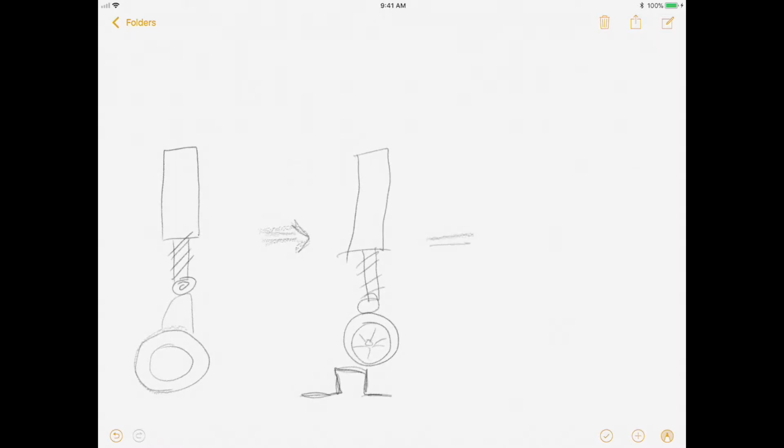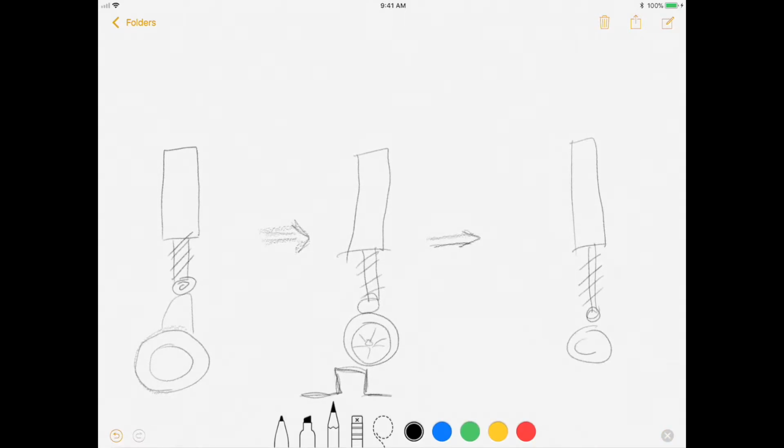And thirdly, maybe we want to design an active suspension where an actuator is attached to the model and the desired outcome is achieved. For example, we have some hydraulic fluid that has metallic particles in it and is controlled with an electromagnet. This changes the damping coefficient and you have the desired output.